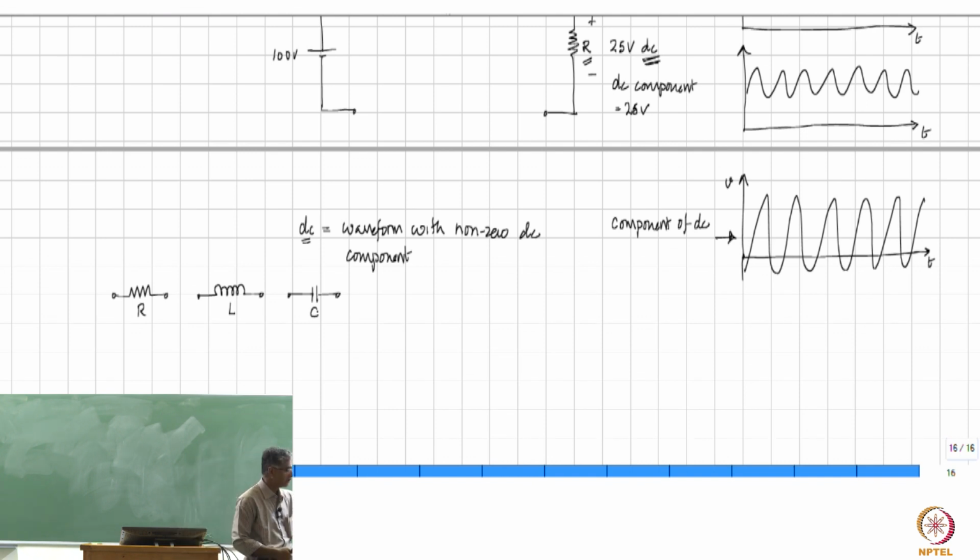Similarly, if you apply a voltage V across the capacitor, half CV squared is the electric field energy that is stored in the capacitor, and if you reduce the supply voltage, you can take that field energy back, right? Whereas in a resistor, if you send a flow of current I, I squared R is lost, gone. Therefore, if we are looking at a circuit with high efficiency, certainly this is not admissible. You cannot use resistors in the circuit.